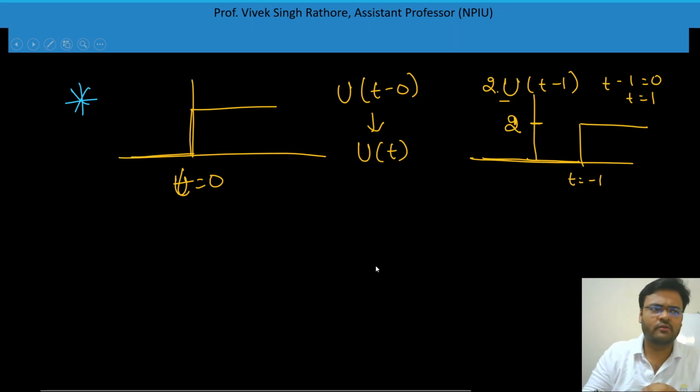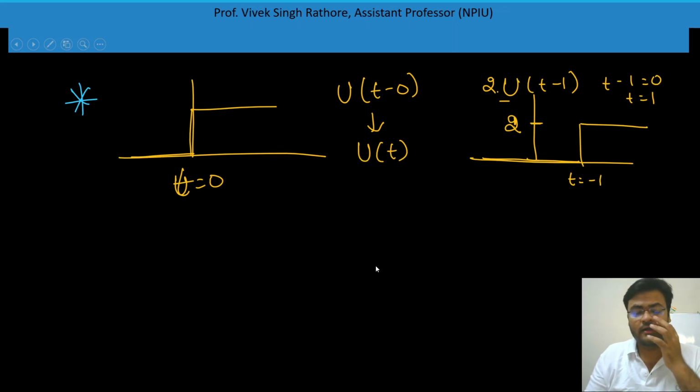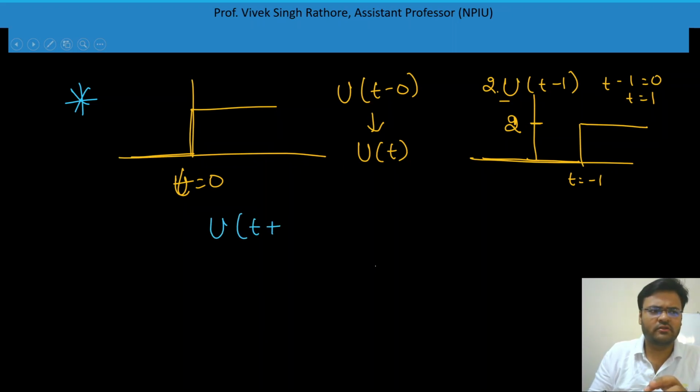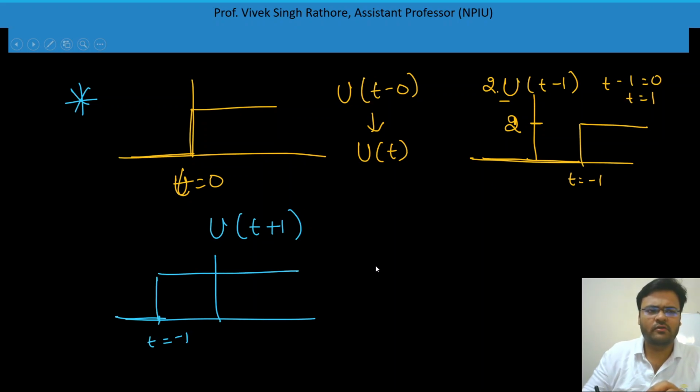Now I think you have understood how we can do time shifting operations on u(t). Now if I tell you to just plot u(t plus 1), then you will tell me, okay sir, at t equal to minus 1 there is a step change, and it will go on. But can you tell me whether it is a finite signal or an infinite signal, meaning is the time duration finite? You will tell me, no sir, it is going on till infinity. This is an infinite duration signal.